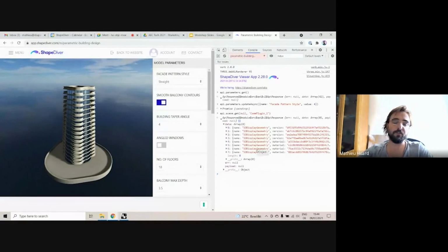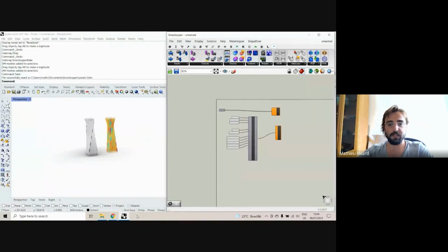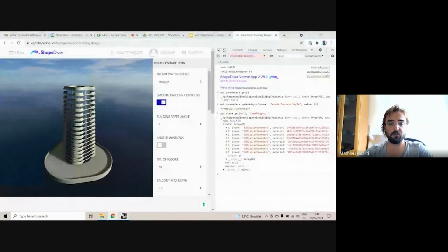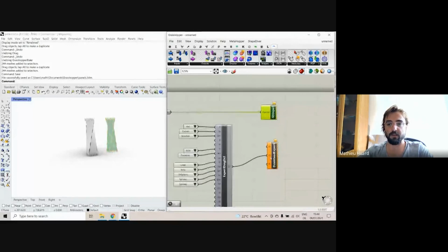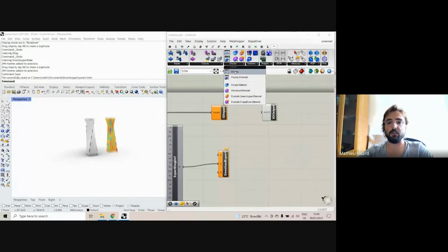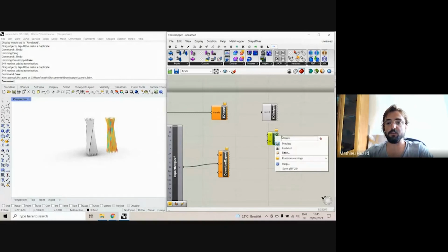this model does not follow the best practice to upload ShapeDiver models, because all the outputs here correspond to output components, right? So in the new plugin, these output components here. In the old plugins, we only had this display component, so that's why. And it used to be called SD display geometry, this component.